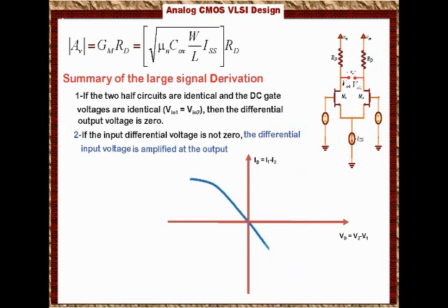By making delta Vn negative, we start to realize that the current ID2 minus ID1 starts to reach saturation toward ISS, which means that all of the current flowing from the biasing current source will be supplying the transistor M2.